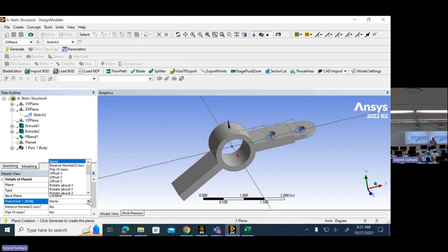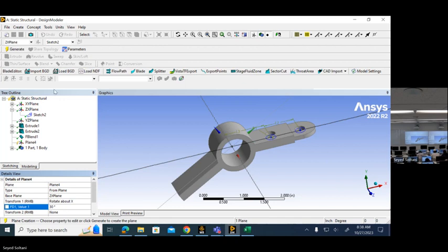But we are doing this around which axis? You see, we are doing these transformations around the axis that you see immediately at the center of the circle, not this one, not the reference coordinate system. So pretty much, if this is my coordinate system, I need to rotate it around this axis by 30 degrees. But what is this axis? You see, this has been color coded, which means that the red is actually the x-axis in this coordinate system. So then I need the rotation by 30 degrees around the x-axis. So rotate around x by 30 degrees and generate the plane.